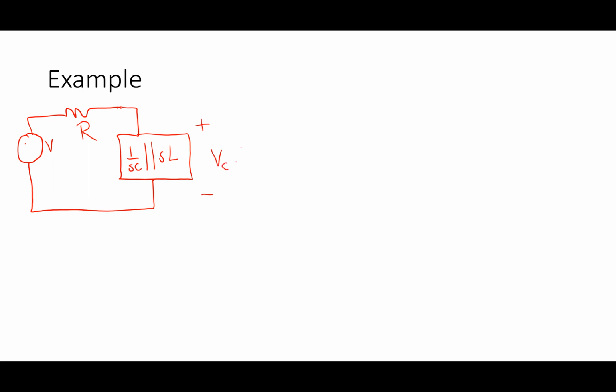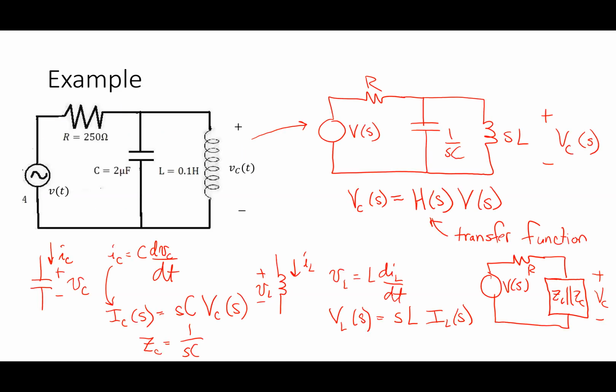But the voltage flowing through that combination. Voltage never flows. Voltage is the pressure that forces things to flow, right? There's water pressure in your house that causes a flow of water. Voltage is the pressure that causes it to flow. The more pressure, the more flow I get against the resistance. Pressure is across something, and this is important: voltage is across, flow is through.